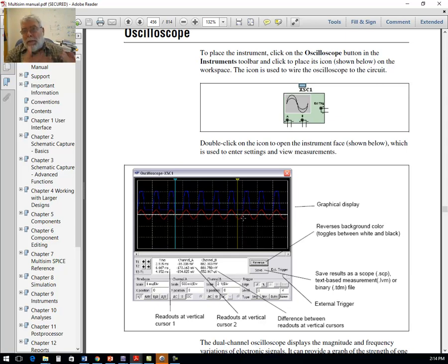One would be the source, and the other one, for instance, in our case, the voltage in the capacitor. So see that essentially we have three things that we need to control there. One is the amplitudes of each one of the signals. So we have the peak-to-peak amplitude that we can select here in the channel A and channel B. And then we have a scale.